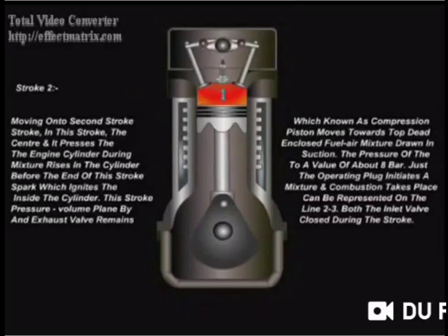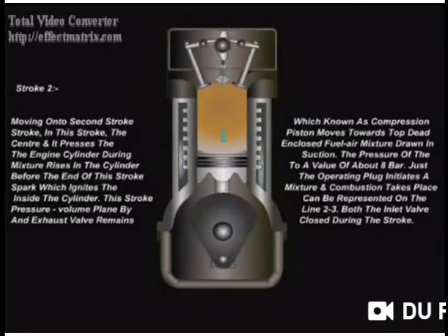Now after the ignition, the air fuel mixture explodes, and here we get the power stroke, and the piston moves from top dead center to bottom dead center, which is called the power stroke. During this stroke, both the valves are closed.